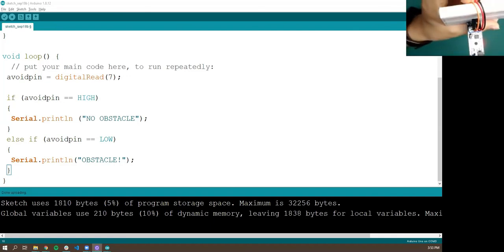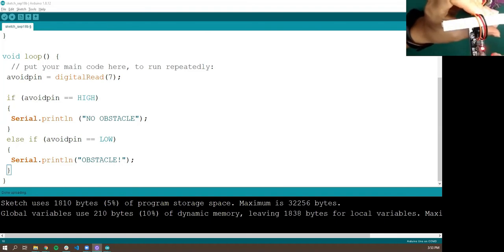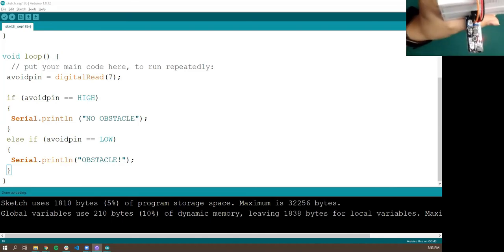So if we try, there is no second LED lighting up. So we will need to adjust the reflectivity first, then we will adjust the sensitivity. So for reflectivity, which is the port 502, we will need to adjust all the way clockwise. So change here. So we will try from here first.